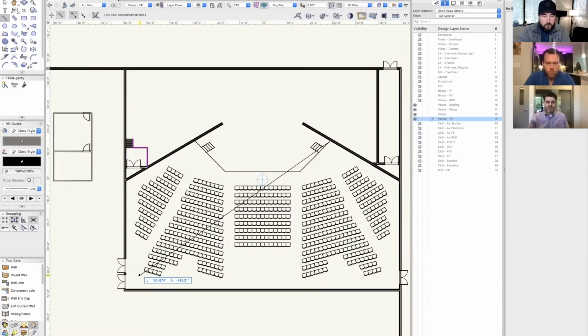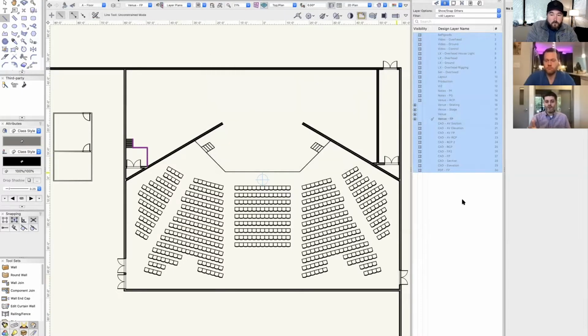That measurement dictates what we would call the furthest viewer. And the formula for figuring this out is that the furthest viewer is 8 times the height of the screen. What we found is that up to 10 times the screen height is acceptable, but 8 times the height is going to be the ideal. So in a situation like this, where your furthest viewer is roughly about 100 feet, which is what we measured, we're going to want the screen to be at least 8 feet tall. And then we'll just play with it. We'll look at it, because there is a little bit of consideration that goes into this: it may be technically, objectively the perfect size, but inside the room, it might look a little strange.